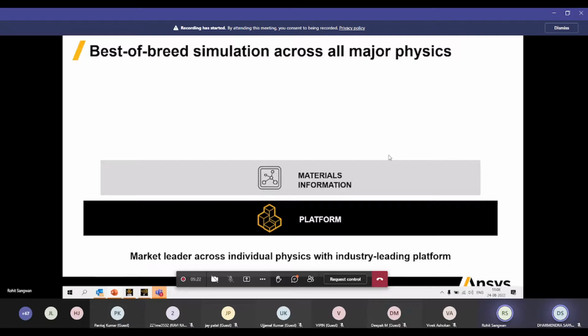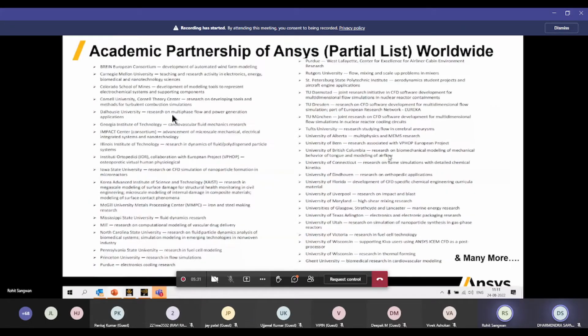If we come to the fluid domain only, as we are discussing CFD, we have a basic process. We do geometry, then meshing, then the solver, and then post-processing. So there are 3 processes in CFD: pre-process, solve, and post-processing. In pre-process we go for geometry modeling, CAD. Just like CAD, we have other CAD tools, CATIA, UG NX. We can import that file and start work on it, or we can create our design itself in geometry, SpaceClaim, or DesignModeler.